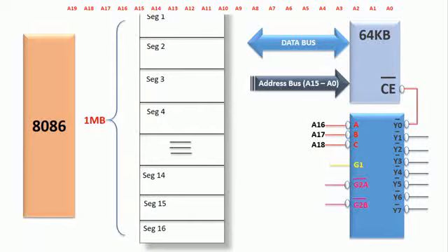Okay, now. So depending on the enabling connection, depending on the A19 position, whether you are using A19 to enable the active high signal or to enable the active low signal, this memory device may be mapped to segment 1, that is the initial segment positions, or may be mapped to the final segment positions. Okay, now let me show you how.